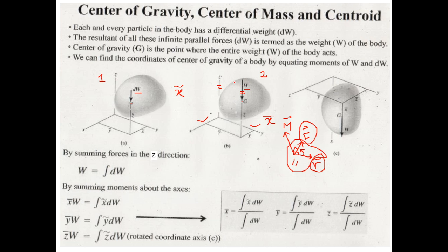And why is this true? Because of the definition of the cross product. If the force and moment arm share this plane, then the moment can never lie in this plane; it will always be perpendicular to this plane. So if this w has exactly the direction of the z-axis, it can never produce moment about the z-axis. This is the logical reasoning why a force never produces moment about the axis to which it is parallel.